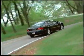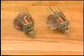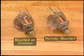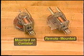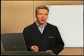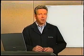Beginning in the 2002 model year, another form of leak detection is going to be phased in. All vehicles having the next generation controller will use a system of natural vacuum leak detection, or NVLD. Unlike LDP, on vehicles with NVLD, the EVAP monitor is run during system cooldown. Essentially, what this does is create vacuum as the evaporative system cools. If no vacuum occurs over a period of time, the PCM determines that a leak exists.